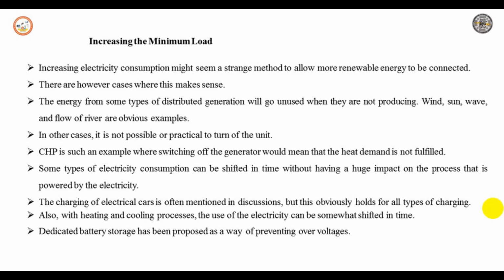voltage directly to control the load in a similar way as the power frequency control with conventional generators. A high voltage point will have a surplus of power, which is compensated by an increase in the consumption. Also, under voltage could be mitigated in this way with electric cars. So charging would go faster when voltage is high, and slower when the voltage is low. Some control algorithm could be implemented in the charger, and heating and cooling load. As a result, the indoor temperature would depend on the voltage of the grid.